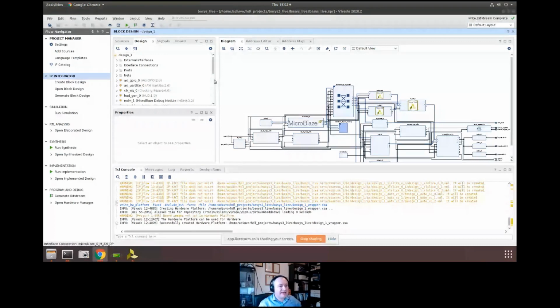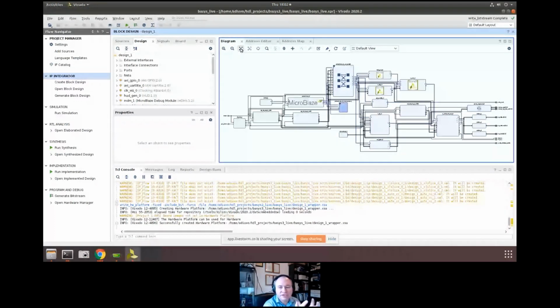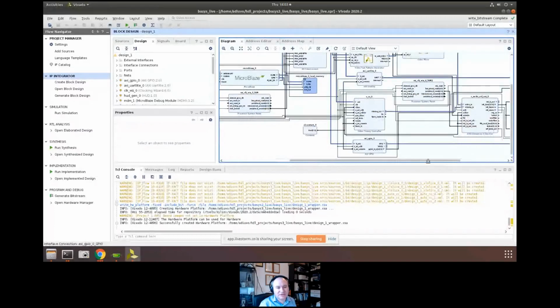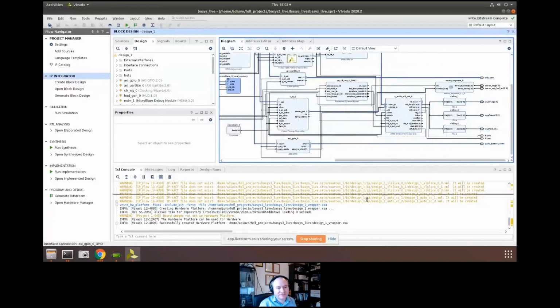So remembering back to last time, in our Vivado project we created this MicroBlaze system that has the custom test pattern generator IP in there, and you can see these up here in our design. We've got the test pattern generator here to generate the background. We've got the custom heads-up display, we were calling it, and that's going to draw the bat and the ball on the screen. And then we have the mixer element here that's going to mix those two videos together and create an output stream. The output stream, of course, would be generated by these elements.